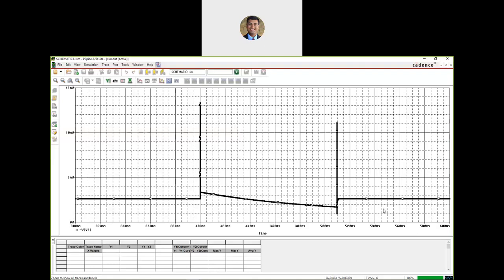Most of the time is spent when the switch is not being pressed, but there is a 110 millisecond time window during which the switch is actually being pressed. And because that capacitor is charging, you see that power transition from one value to the other. It changes because the capacitor is charging during that time, from 0 to 2/3 VCC.